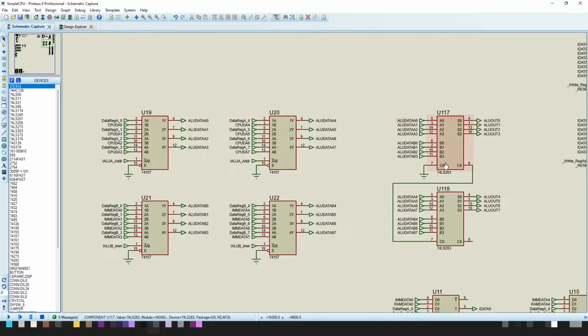Anyway, so these two adders here have two different separate 4-bit inputs, and these 4-bit inputs here and here, if I can select them, thank you very much, these two separate 4-bit inputs actually come from two pairs of demultiplexers. Remember the definition for the ALU inputs allows me to select two different values depending on if it's input A or input B. Remember that from the initial design.